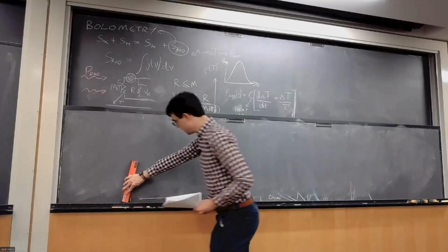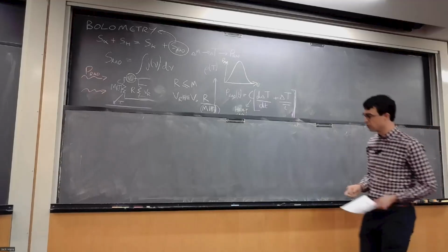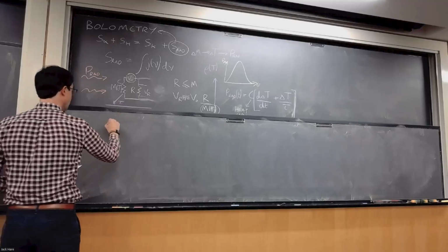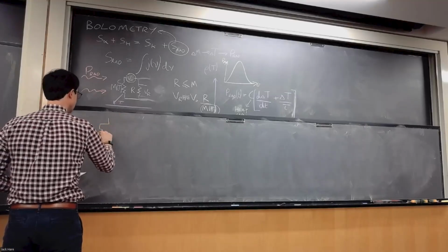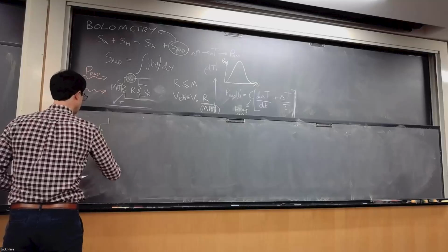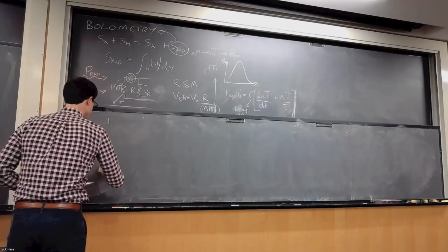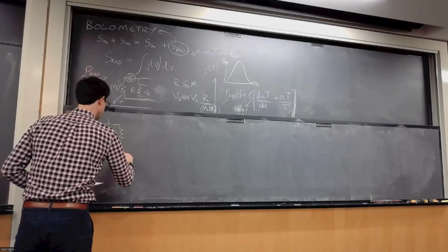So what we do to make this measurement more precise is first we do two things. First of all, we do something called a Wheatstone bridge, which many of you have come across before. A Wheatstone bridge is an arrangement of 4 resistors. So there's a resistor here, another resistor here, a resistor here, and another resistor here.